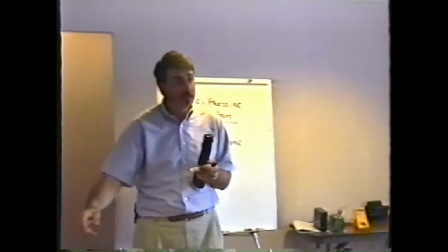Let's say we have a resistor that's green, red, orange. Beautiful orange, all right. Green is 5, red, orange, 3. 523 ohms, right? No, Randy, you dumb shit. What is it? It's three zeros, right? 1, 2, 3, 52,000 ohms. Okay, let's do a couple more.